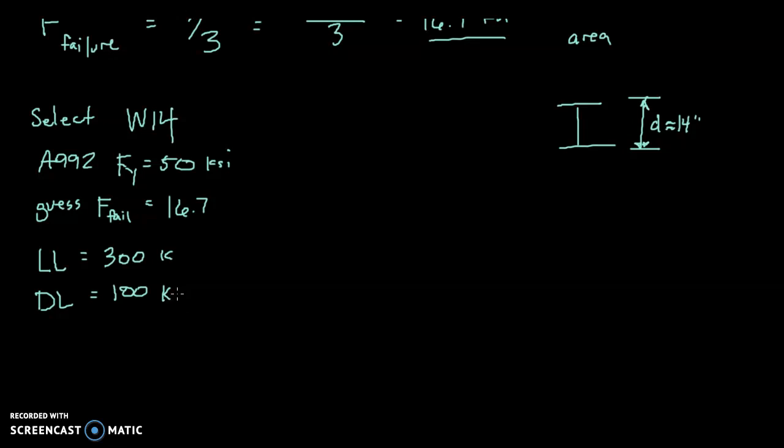But since we are doing allowable stress design, we don't really need to separate these out. So although the problem gave it to us like this, we really just need to know that the total load is 400 kips.